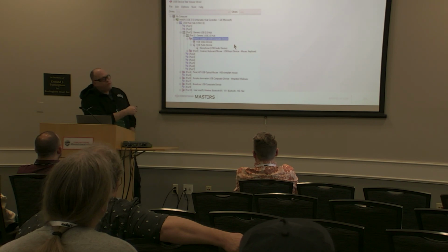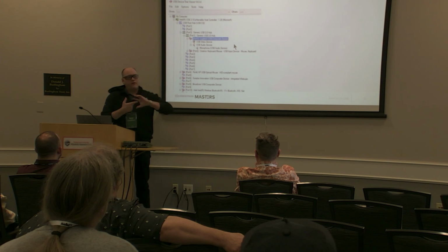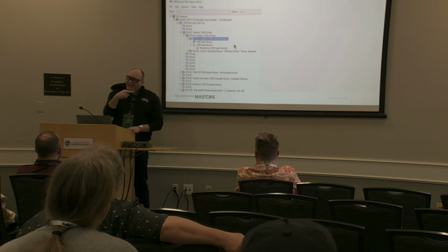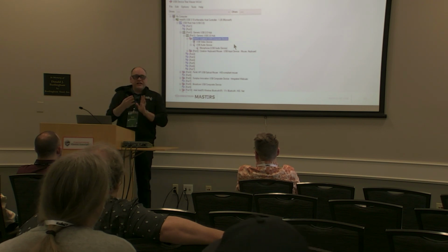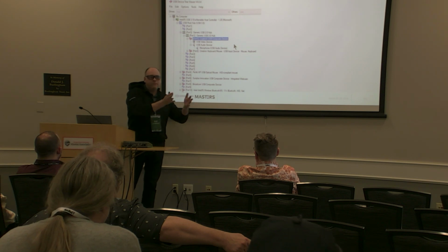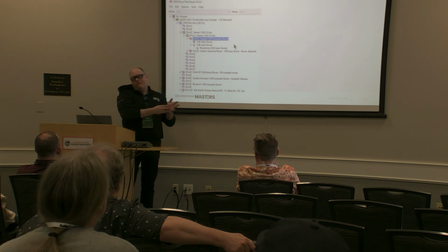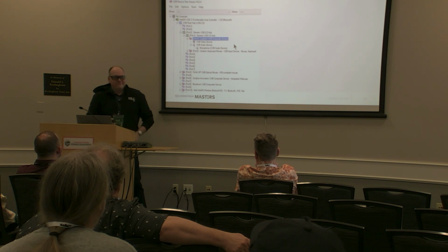Now, why do we have more than 4 ports on a hub here? Well, they're virtual ports, right? So when you plug it in, the host controller, if it's capable of doing this, will say, okay, I need this port to be a USB 2 port and this port to be USB 3. But remember, those lanes are on all the switches. So if it's getting data on just the USB 2 lane, then it's going to put you in one of the virtual hubs, or virtual ports on that hub, right? So it's still only 4 ports.